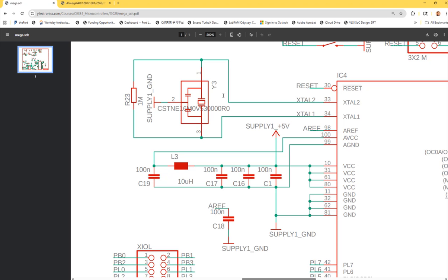So this one, $17, all right, has an external oscillator, 16 megahertz. That's the little tiny thing. If you look at the board, you can see that little tiny shiny one, right? Silver colored little tiny thing. That's the oscillator with 3 pins. You have soldered it, right, by yourself. That's the oscillator. Has the internal capacitors. That's the oscillator itself and capacitors.